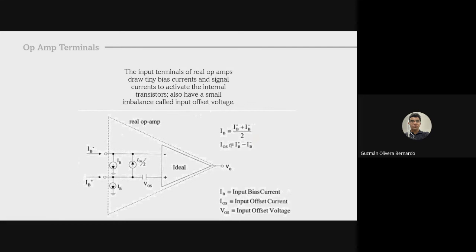Most operational amplifiers, like the 741, have internal circuitry that automatically limits current drawn from the output terminal. Even with a short circuit for resistance, output current is limited to about 25 milliamperes. This feature prevents destruction of the operational amplifier in the event of a short circuit.